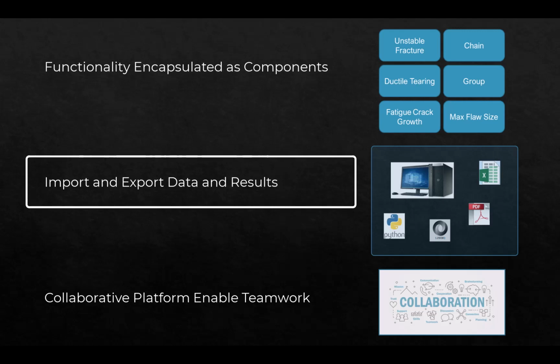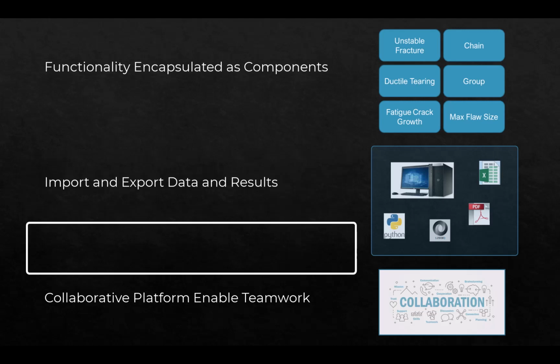Next, Material ECA results can be exported directly as Microsoft Excel workbooks, and automatically generated reports can be exported as PDF files. Furthermore, Material ECA data and results formatted as JSON can be imported and exported. This means we can programmatically get and process data from various sources, such as spreadsheets, databases, or miscellaneous data files, into Material ECA. Simple Python scripts were used for the 2 examples mentioned earlier. This saves time, improves quality, and makes results far more useful.